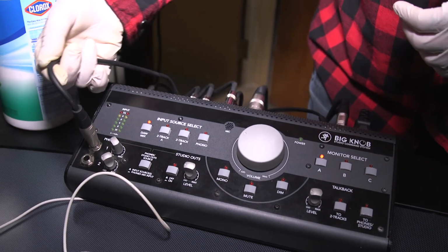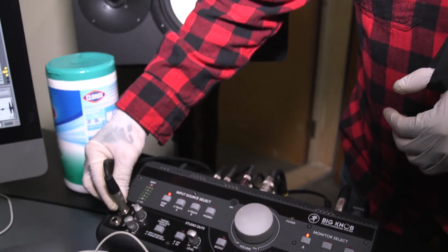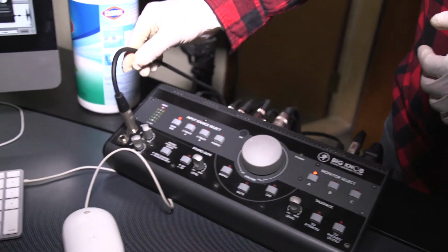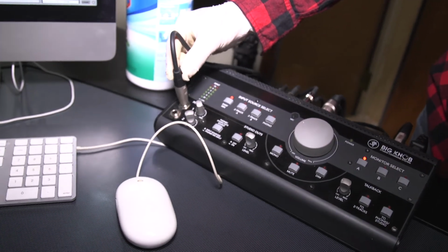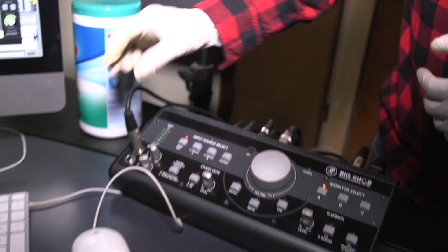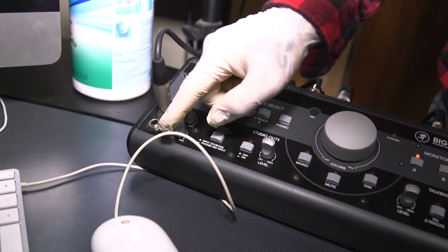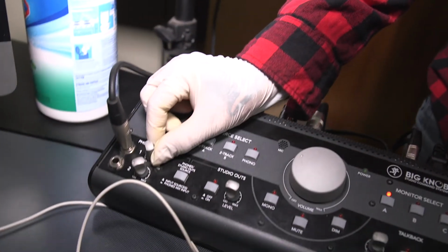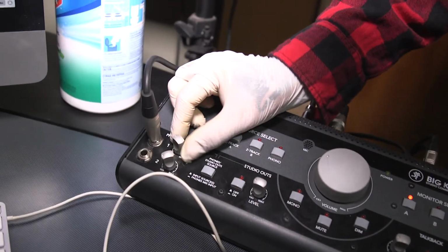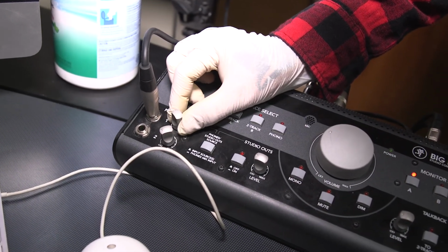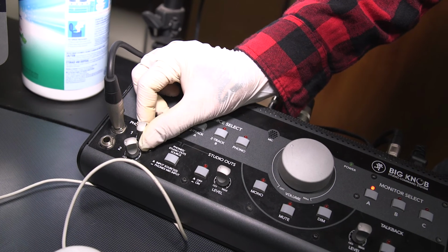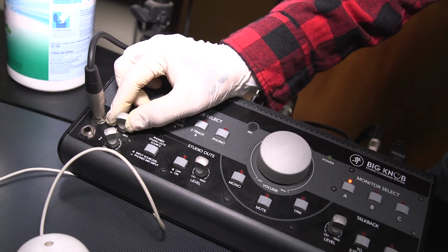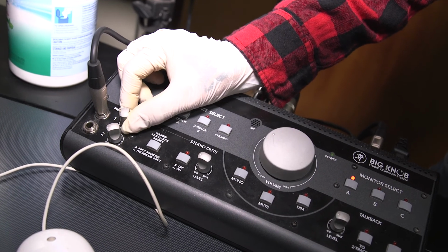Now this cable right here is going out to our headphones. When we were on the other side of the patch bay, I was talking about our headphone extension cable. That's where this is being connected to. So we have two headphone outputs on this Mackie Big Knob, and we just have one of them that we're using, and this is output 1. This is the level that your talent is going to be hearing in the studio. So if they need more volume, this is where you're going to turn up the volume. If they need less volume, this is where you're going to turn that down.